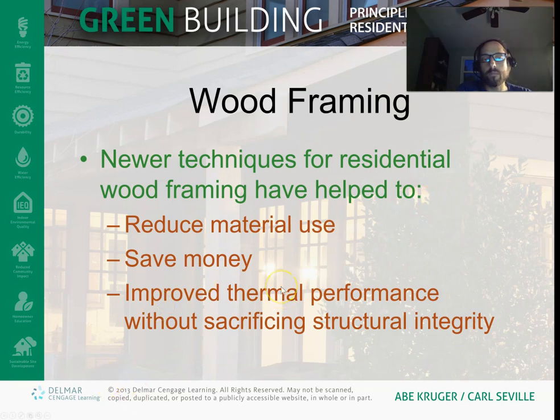So they do go into some of the more advanced framing techniques in the book. And this is becoming a little more common, although we're still just generally building the same way that we have been for the last 50 years. 16 on center studs and double top plates and so forth. So this is kind of a burgeoning movement, especially in the green building movement, to do these advanced or smart framing techniques, and they will get into that a little bit.